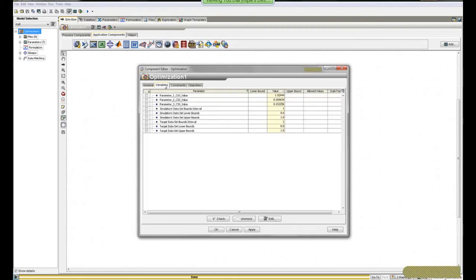I go over to the design variables, and all I have to do is tell it that I'm going to use the C10, 20, and 30 values. As we showed in the PowerPoint, you don't have to set a lower and upper bound, but it can be quite useful. Because of my experiences with elastomers, I have a sense of what they should be. Sometimes it is, I know this is overly stiff behavior, which is why the upper bound I'm going to set to be 1.9244.